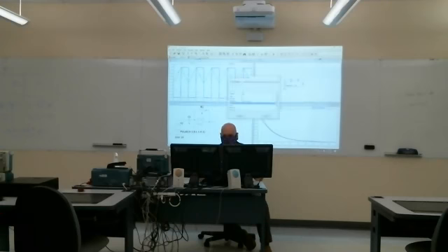Okay, so if I switch it over to the default, or actually make it the 741. One thing you'll notice right off is that the output's following the input, which surprises me, but it's wrong. Using the 741 model, I have to include the power supplies.